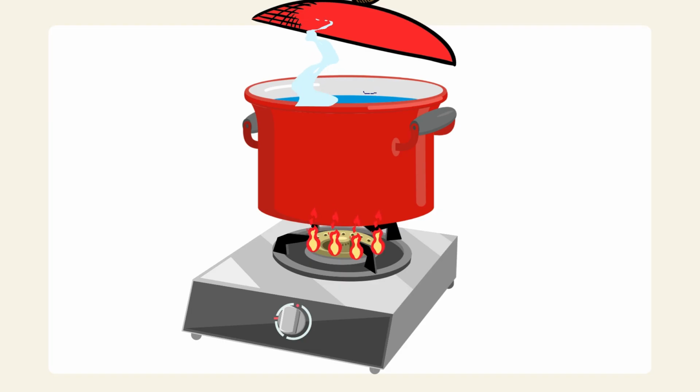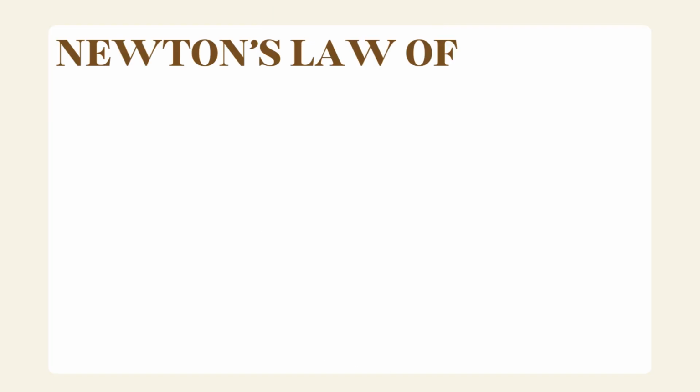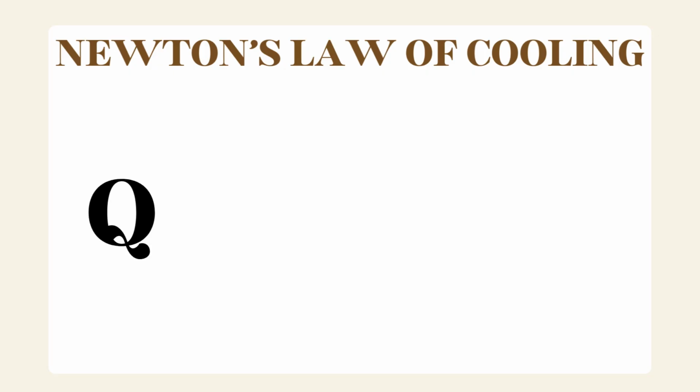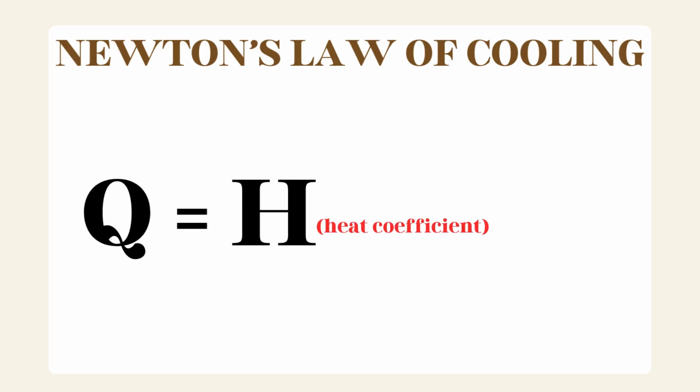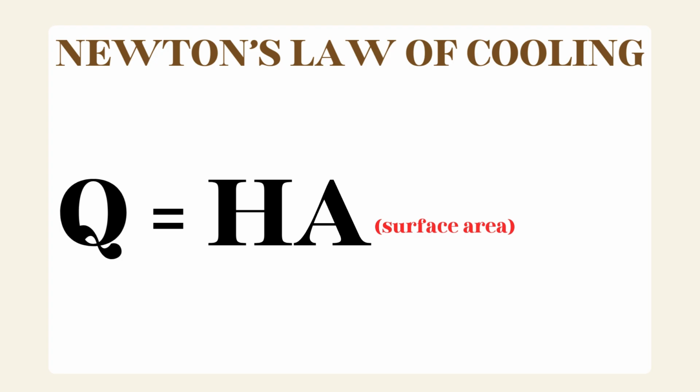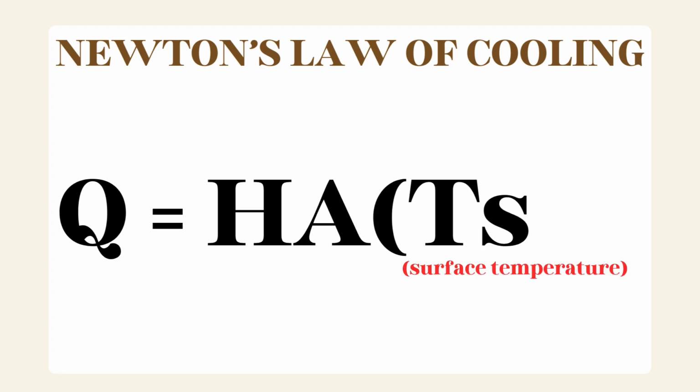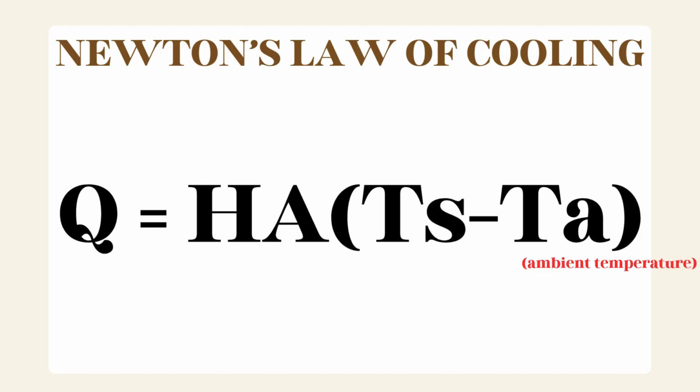The equation for convection is Newton's law of cooling, where Q is equal to the heat transfer coefficient multiplied by the surface area for heat exchange, multiplied by (surface temperature minus ambient temperature). Let's try solving a problem using Newton's law of cooling.